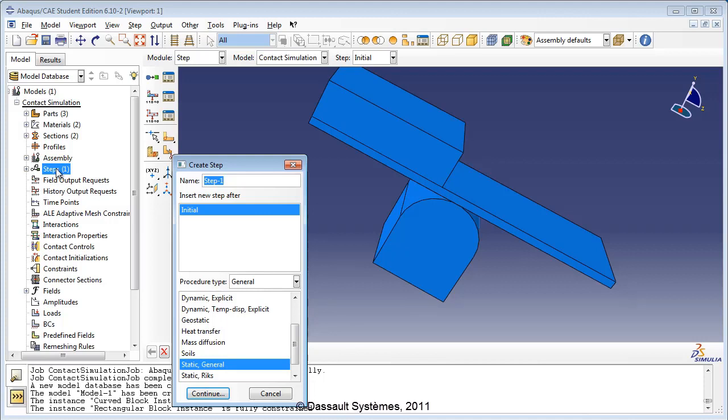It is best to establish contact between the components in a reasonably smooth manner, avoiding large overclosures and rapid changes in contact pressure, and one way to do this is to include more steps in the analysis to move the components into contact before fully loading them. This makes setting up the model a little harder, but the solution will be much more efficient. The part instances that are in contact have been placed face-to-face in the assembly. There are two ways to establish the contact. The first is by applying a small force on one instance to bring it in contact with the other. The second option is to use a boundary condition to displace one part closer to another by a small amount to bring them in contact. We use the second option.